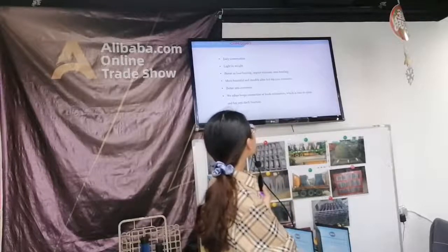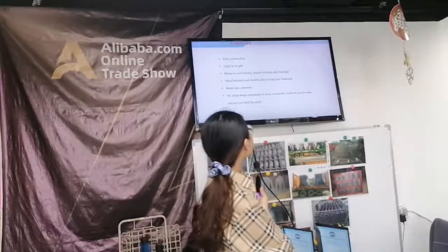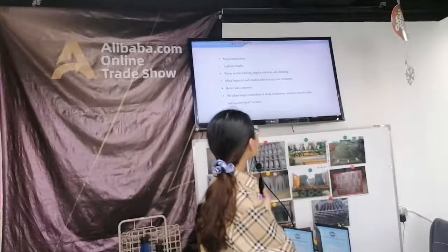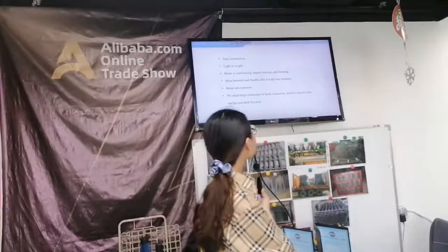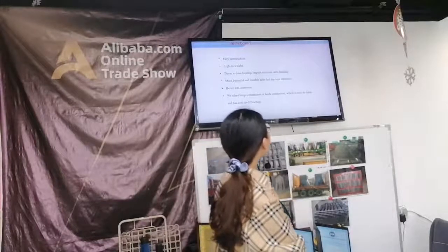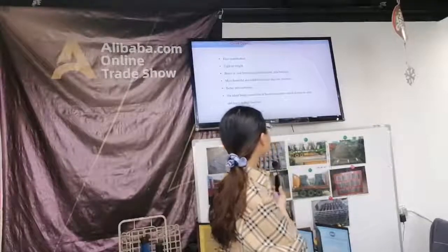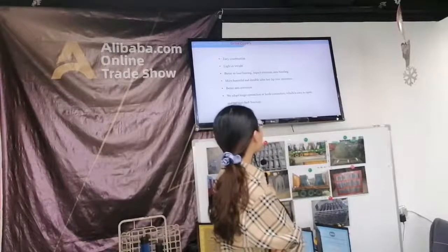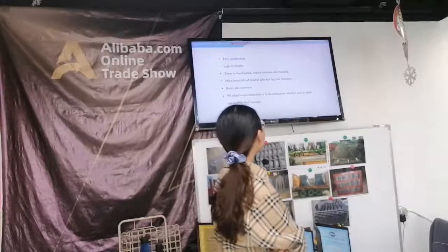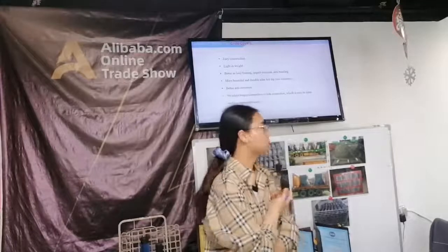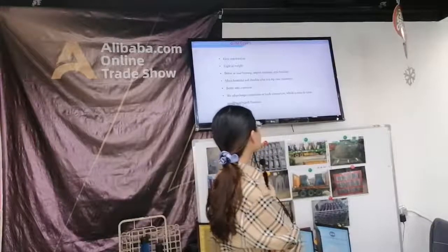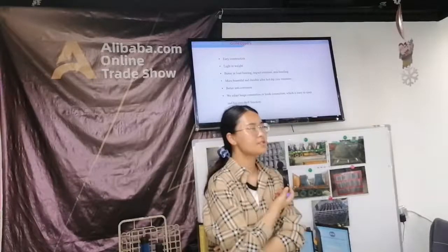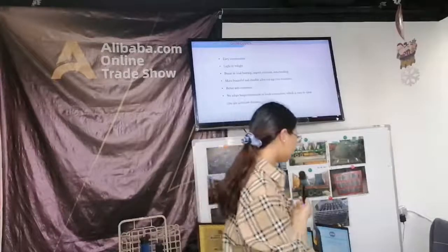For grip covers, it is very easy in construction, light in weight. It has better load bearing, impact resistance, and anti-bending. It is very beautiful and durable after hot dip galvanizing treatment. It has better anti-corrosion. We adopt pin meshing or hook meshing, which is easy to install and has an anti-theft connection function.